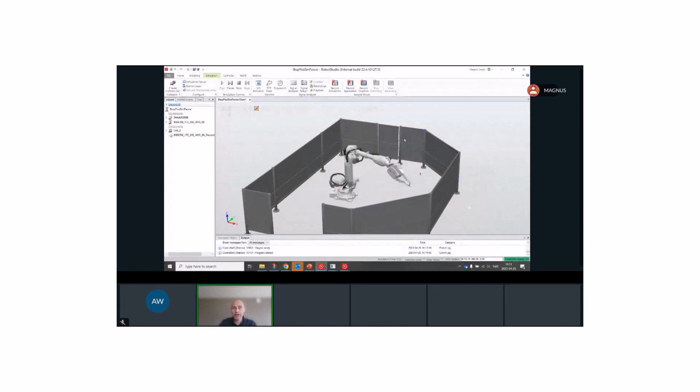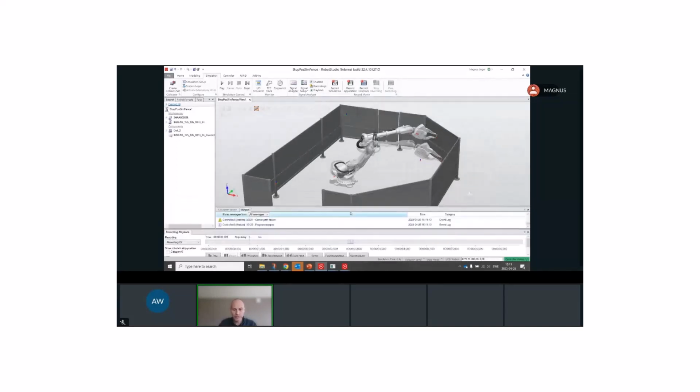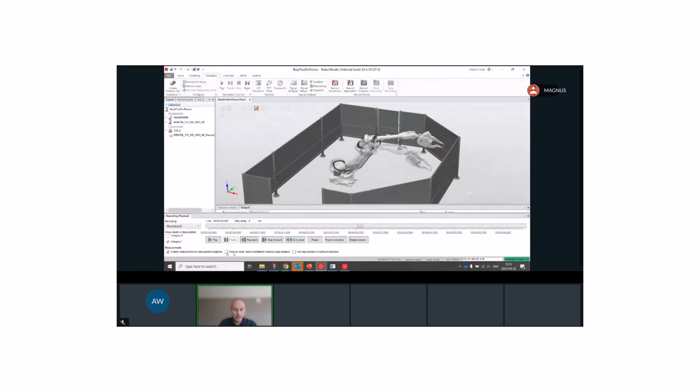And I will bring up a new feature that we introduced last year, for the playback. Let me see if I can just turn it here. And that gives you an idea that you can move around with the latest recording. You can also turn on the stop positions, and you can see that at each of these ticks, you see exactly where the robot will come to a stop. So I just drag that, and we can also measure how far away. And you can see moving around, it needs almost 2 meters to come to a stop with the speed, load, and inertia, and so forth.